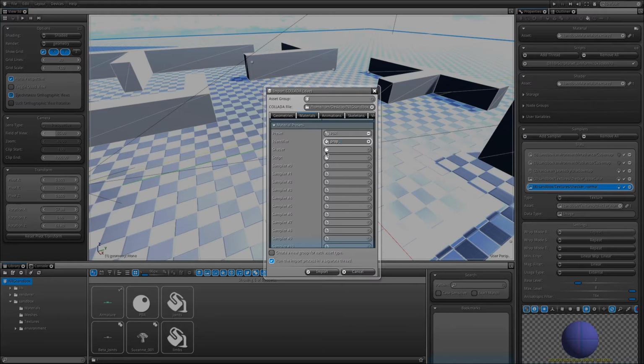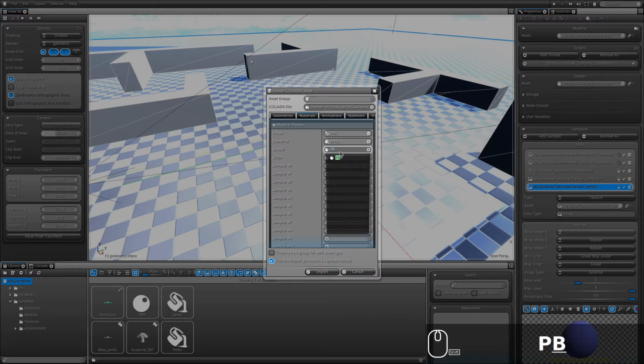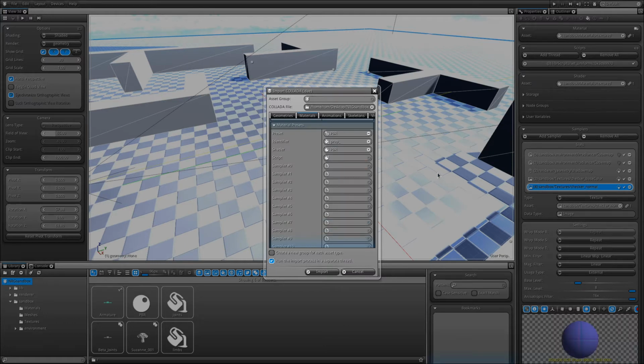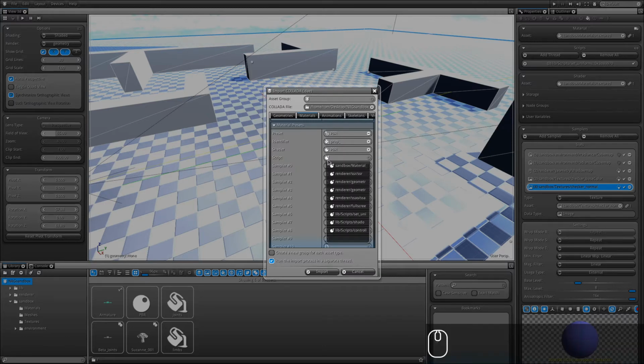And as the shader, we are going to connect our newly created PBR shader that gives us a boost by having the base color and normal already handled in code. And as a script, since each and every material is connected to the uniform that is going to send us, as I was explaining in the previous video, the sun position, the sun direction, the camera position, and so on, we are going to connect that as well. So our new material will also have a new thread created with the set uniform script already assigned.